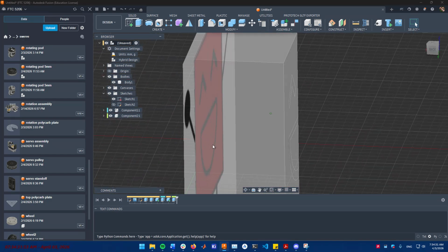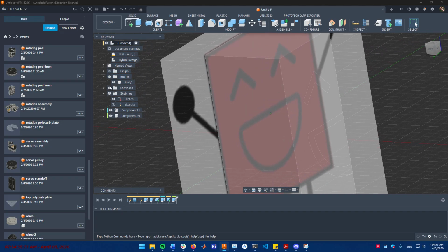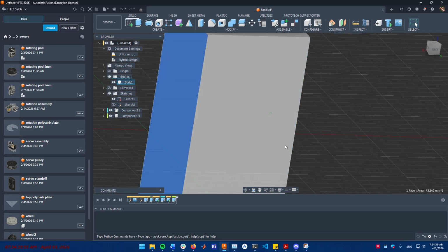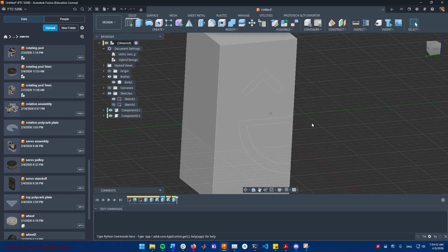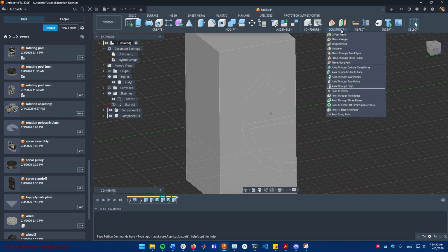So first, notice that I'm sure you want the pixel's arms to be in the middle here instead of being at the end, because that would look really wonky. And to do that, we have to define a custom plane to start the sketch at. So first we will construct a midplane, which creates a construction plane at the midpoint between two faces or planes.